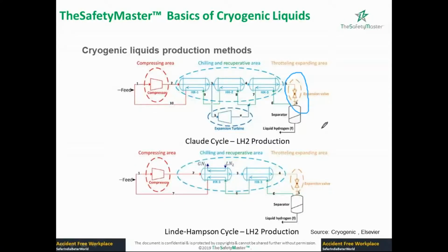My last question, sir. Is there any standard for storing cryogenic liquid? The moment you want to store a cryogenic liquid in a tanker, it comes under pressure vessel. If the pressure is beyond a particular point, it comes under pressure vessel, so you use ASME Section 8.